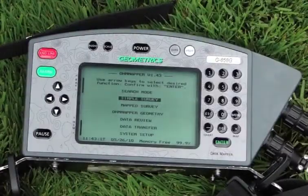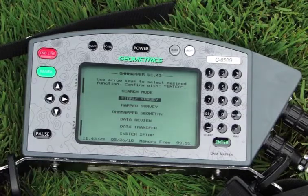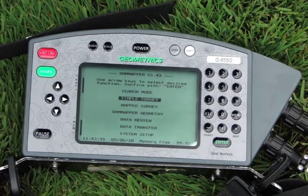This is a simple survey for when you're collecting a bunch of lines, but the console has no knowledge of your mark spacing, your line length, or any of your grid information. So when you're using simple survey, you need to be taking good notes so that you know line 1 is 100 meters long, mark spacing is 10 meters, etc.